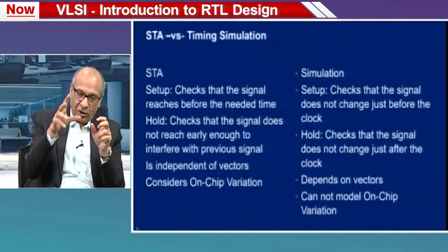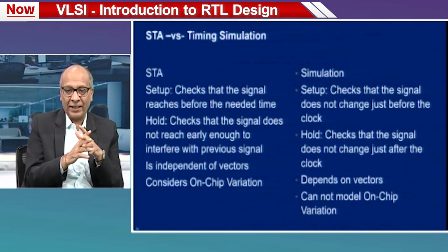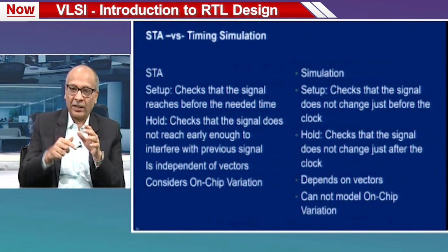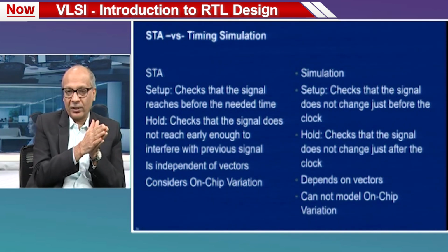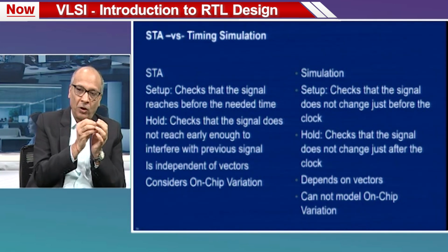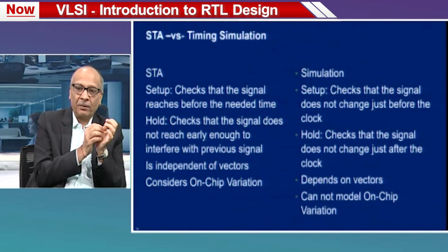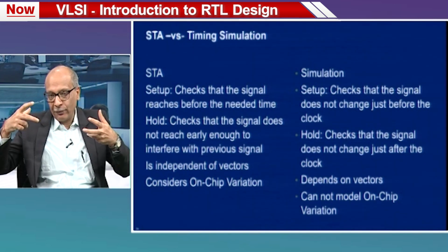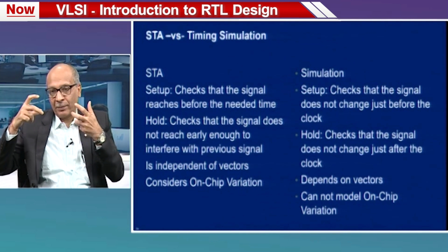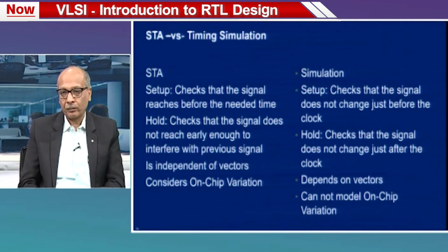This difference may not be so apparent to you when you read these slides, but we will explain this difference slightly later in the next slide. Similarly, hold, the STA definition is slightly different. Hold checks that the signal should not reach early enough to interfere with the previous signals. So, there is a fundamental difference in how the setup and hold is defined between simulation and STA.